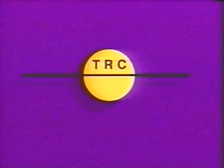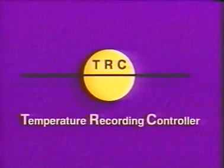The letter identification for an instrument symbol is usually arranged in this order. A circle indicates the instrument. The letter of the variable being controlled appears to the left. If the instrument records or indicates, this is indicated by a middle letter. The letter on the right side tells you the instrument that does the job. The letters in this instrument symbol stand for temperature recording controller. The number of the control loop, if any, is shown in the bottom of the symbol.